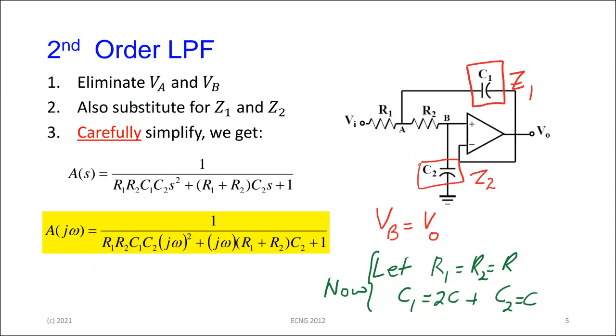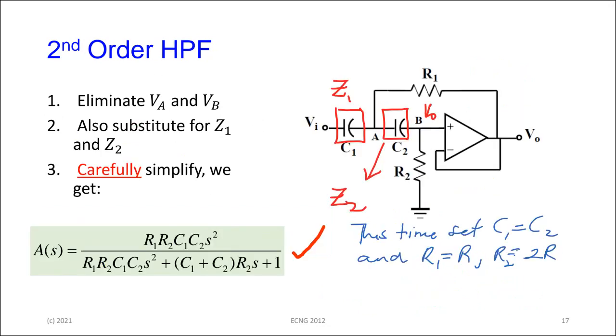So in the low pass case, we have R1 plus R2 multiplied by C2. In the high pass case, we have C1 plus C2, all multiplied by R2. And of course, we're going to have the pole appearing on the top there. So just a little way of helping you to recall the two of them.